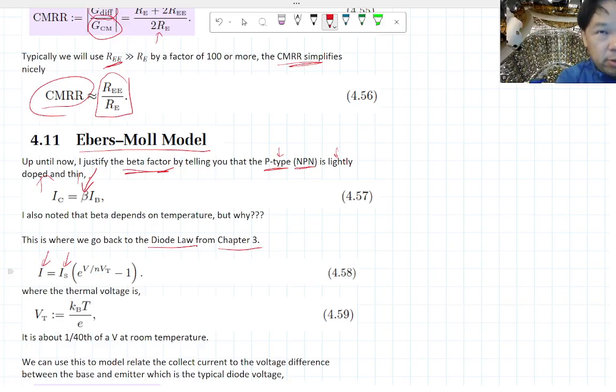But you don't want that to be 0, because otherwise you don't get a transistor, or actually in this case just a diode. And this current gets amplified exponentially if you put a voltage across it, where V is the voltage across that diode, and N is this idealization factor between 1 and 2.